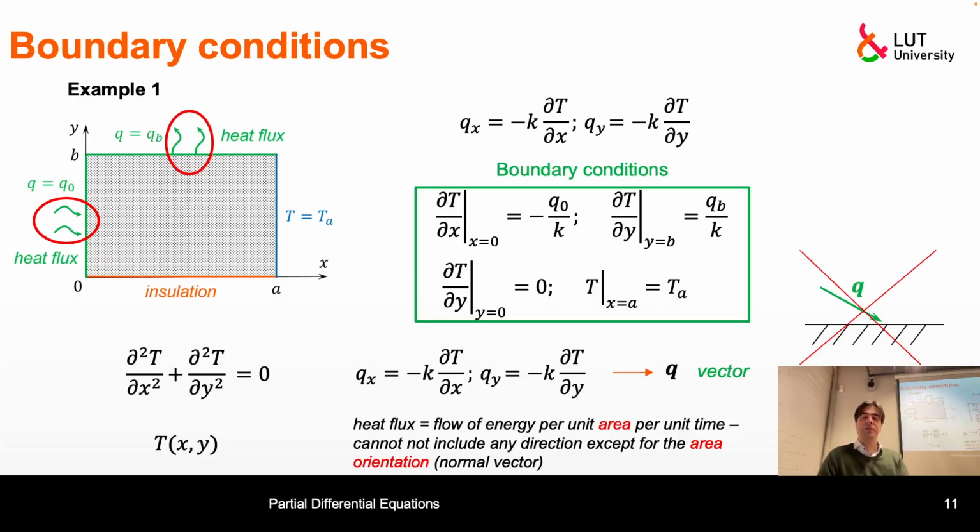So if we were talking about stresses, then I could draw this type of picture and say, okay, knowing the direction of a plane, and knowing the stress tensor, a second order tensor, I can define three components of the vector of the force which is acting on that plane. So there are two directions: direction about orientation of the plane and direction about the force that is acting. And it's similar in this case, but a little bit more simple, but sometimes it causes confusion. That's why I'm talking about it.